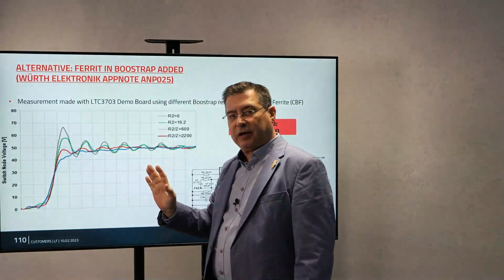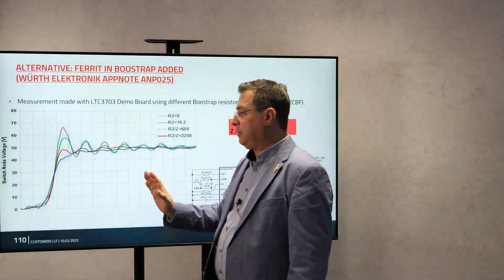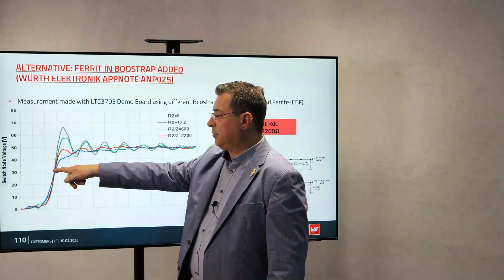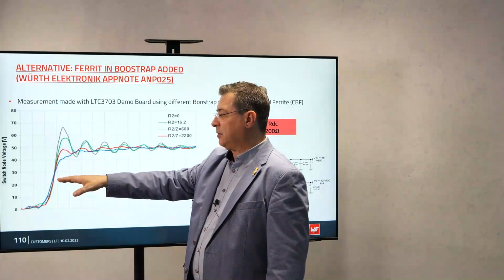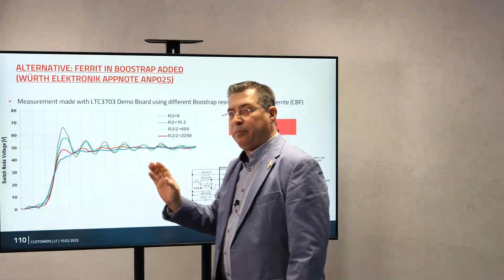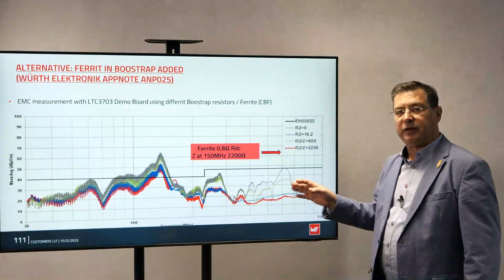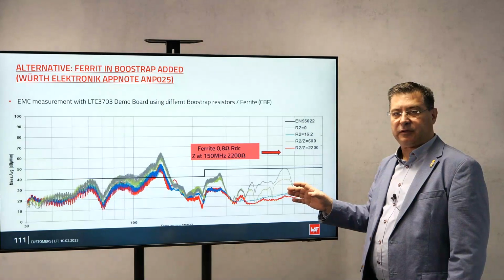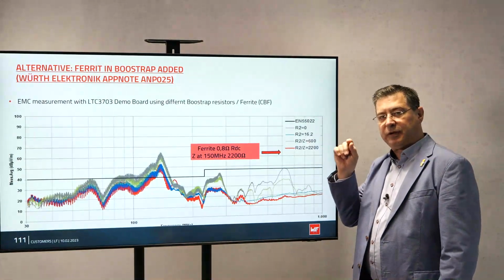It has a small inductance, a few microhenry, but the switching is happening already somewhere like here. So this is not a big issue of delay. The big issue is in the EMC chamber when you make the measurement. The same DC-DC converter, only changing one single passive component.